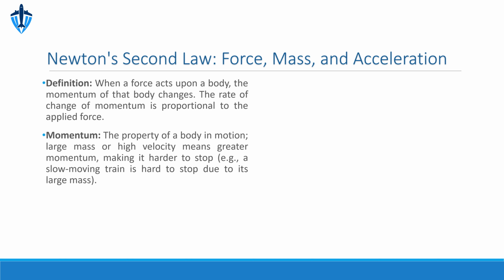Due to these immense speeds, the centripetal forces generated are enormous, causing the blades to experience thousands of Gs. This extreme force is why aerospace engineers must use incredibly strong, lightweight, and heat-resistant materials and design components with absolute precision to ensure they can withstand these stresses without failing. It's a prime example of physics directly impacting aircraft safety and performance.